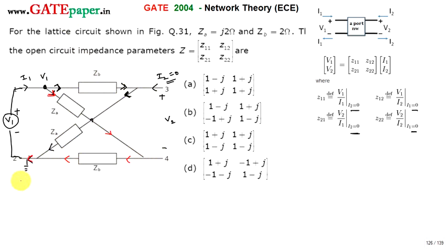So now applying KCL at V1: incoming currents equal outgoing currents. Incoming current is I1, which equals the two outgoing currents. Red color indicates V1 divided by the impedance through which the current goes. ZA and ZB are the impedances. So V1 divided by ZA plus ZB, and for the next current, this is also ZB and ZA, so again V1 divided by ZA plus ZB. That you can write as 2 times V1 divided by ZA plus ZB. All these things you get since I2 is equal to 0.